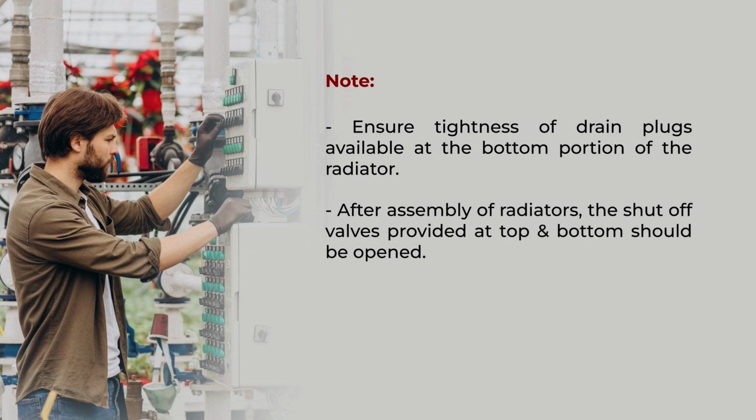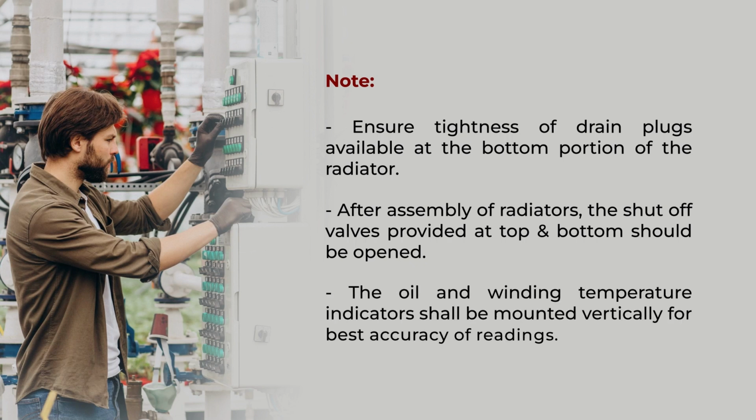After assembly of radiators, the shut-off valves provided at top and bottom should be opened because these valves are normally closed during the transportation from the manufacturing to the site where it has to be installed. The oil and winding temperature indicators shall be mounted vertically for best accuracy of the readings.